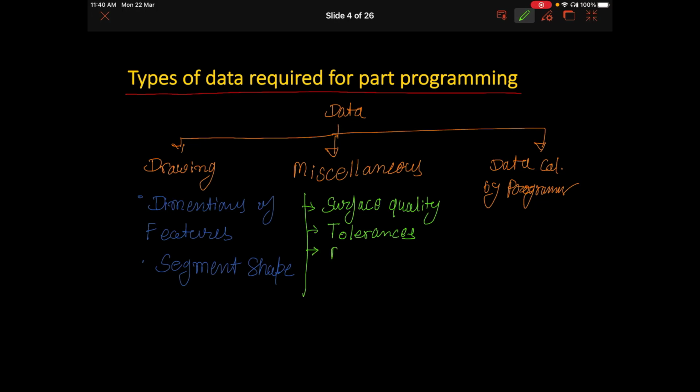So material for tool and workpiece, for both. Okay. We have to determine which material you are going to cut using that CNC machine, and accordingly we have to decide the appropriate tool material also, so that it can remove the metal efficiently and effectively without creating any adverse effect on the machine and the part also.